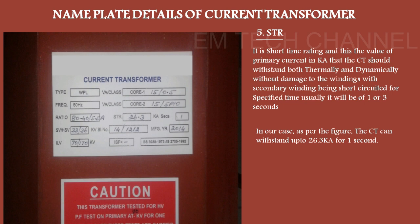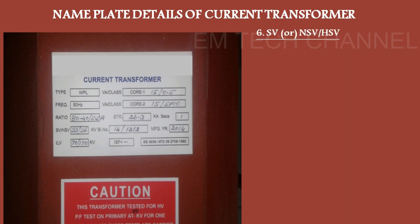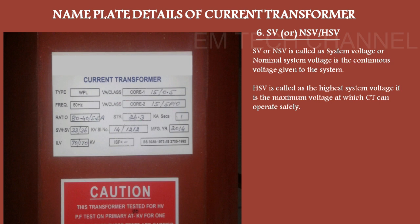Next comes SV or NSV slash HSV. SV means system voltage. Some manufacturers mention it as NSV. NSV means nominal system voltage. It is the normal working voltage of the system. And HSV means highest system voltage. This is the voltage up to which this CT can function without any issue.